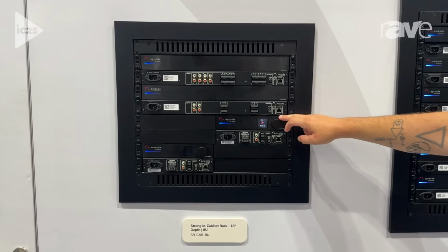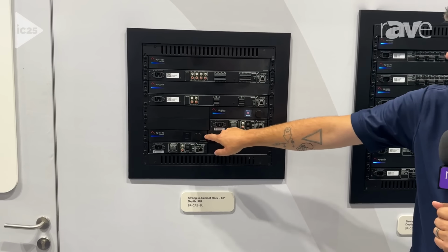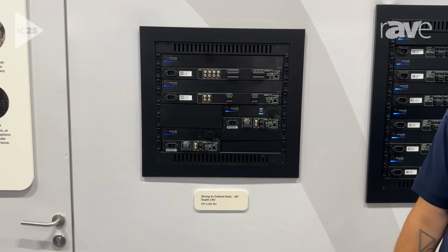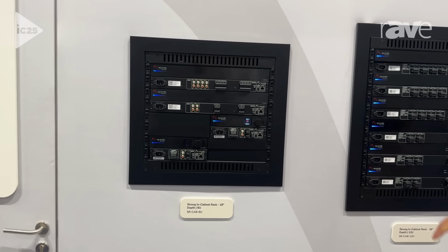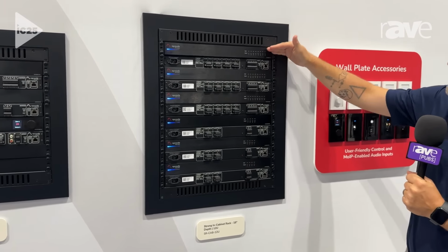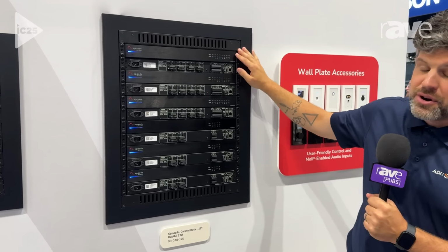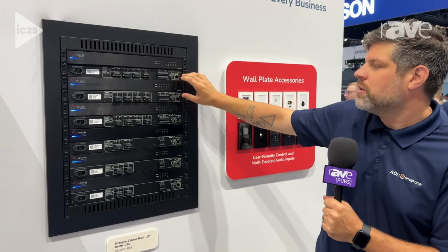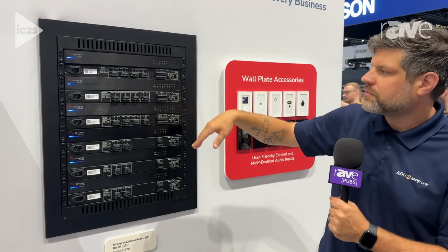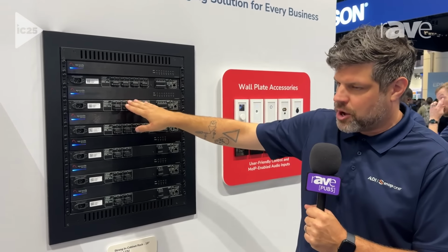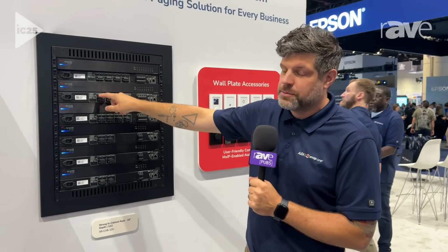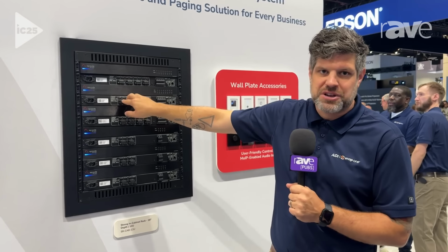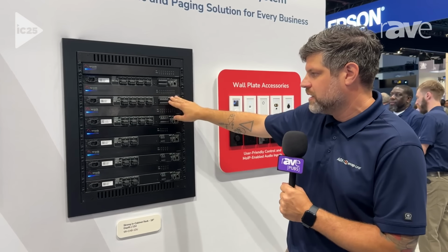The mix amps, they're 2x350 and 2x160, fully controllable via the front panel or IP control for remote control and configuration. The amplifiers, we have 8-channel amps and 4-channel amps in 350 watts per channel, 160 watts per channel, and 80 watts per channel. These are also network configurable and controllable. They are direct drive, so 70 volt, 8 ohm, 100 volt, or 4 ohm, selectable via the local UI or the push button configuration on the back if you don't want to get into the IP settings.